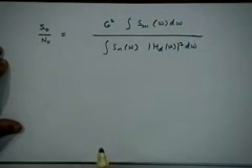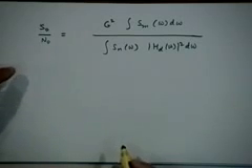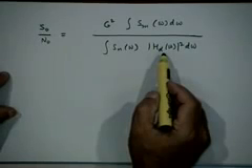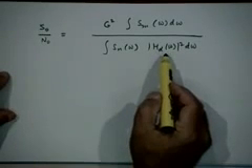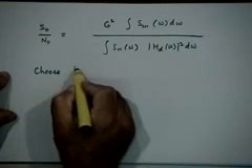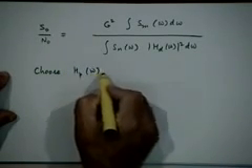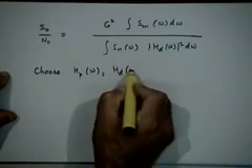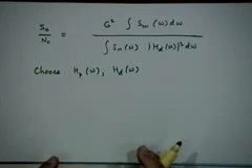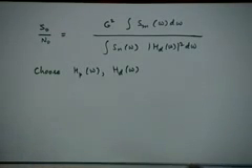Is that okay? And our problem that we want to solve is, we want to choose a pair of filters, pre-emphasis filters and de-emphasis filters, a combination of these two. Of course, we know that this combination satisfies a certain constraint. What is the constraint? That the product of all these 3 transfer functions, Hp omega, Hc omega and Ht omega, should be a constant, right?